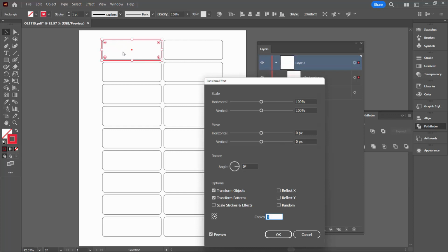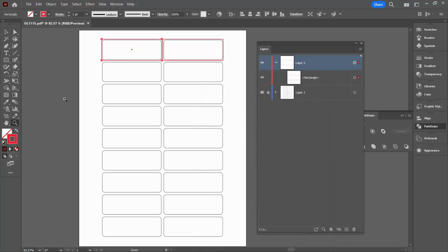And since the box is 221 pixels in size, it's going to have to be moved horizontally at least 221. When I drag over here, the maximum value I can get to is 100. That's the maximum value I can get to if I drag, but if I type, I can go anywhere I like. And if I press the up arrow, I can keep going even further. So what I'm going to do is take this out now to, looks like 224 is going to suit us really well here. Let's just click OK and let's go and have a look at it.